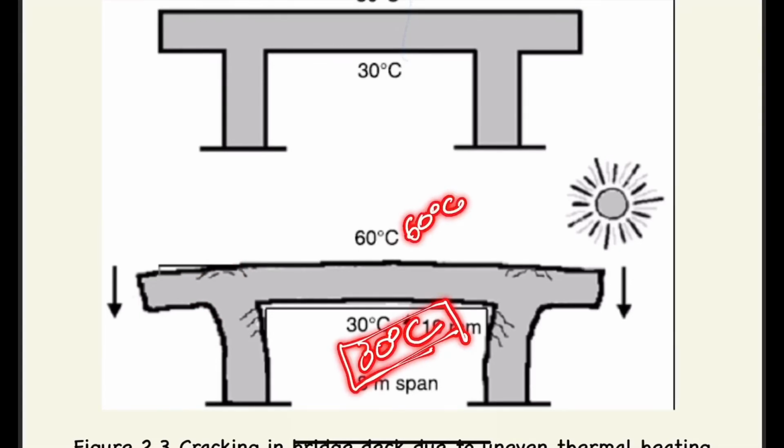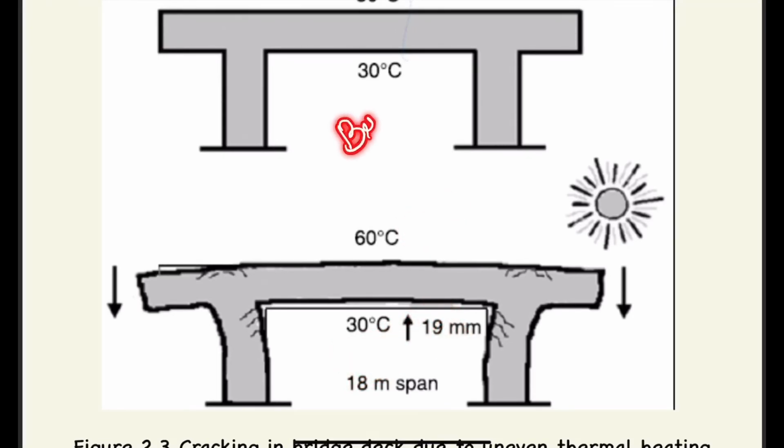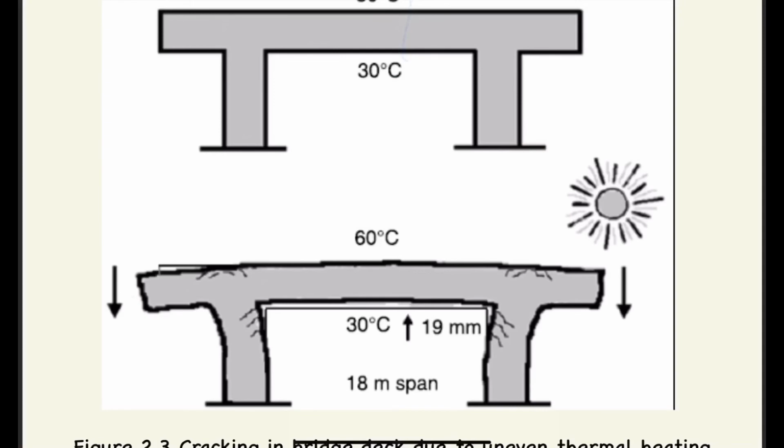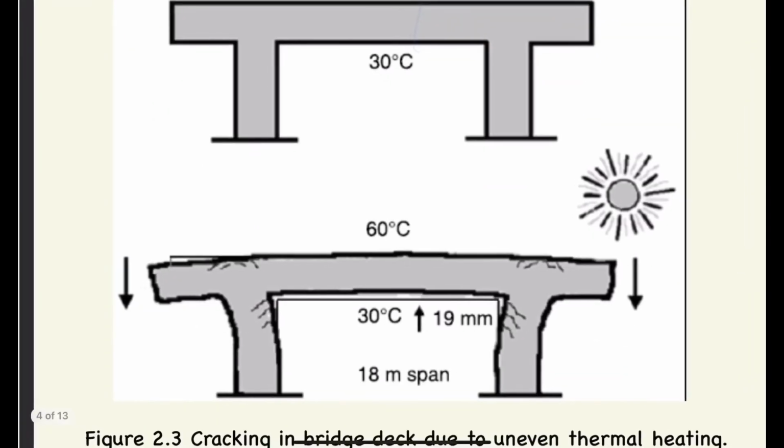So always remember, whenever you go on a bridge, you will see some type of joints in between the bridges. That is what we call an expansion joint. It is also provided for the expansion and contraction due to thermal changes, temperature changes. It is one of the best examples through a figure to understand what generally happens in the general condition.